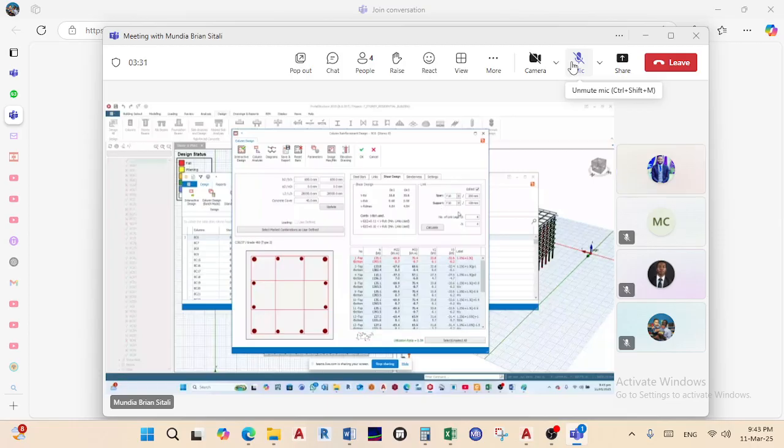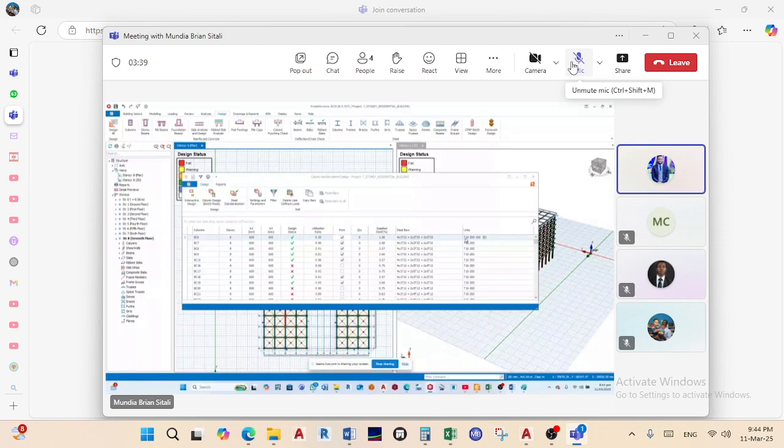Then I say, okay. So you can actually see it here. It says T10 200-100. So the first one, 200, is the span dimension of the stirrups. Then 100 is the support as you go towards the support. Okay, so at this point, we know that all the columns that are in this building are the same size.